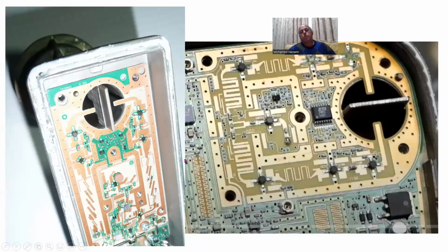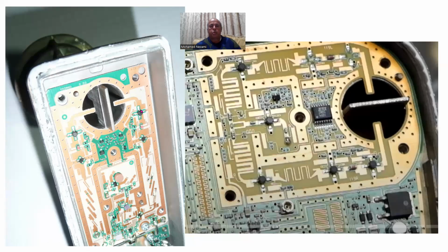Okay, I know we mentioned this in the design of microstrip to waveguide transitions back then. This is an LNB example I just happened to pick up. And on these boards, basically, you've got a circular waveguide and a septum in here, and you can see the steps, here they are. You can see this thing is sticking in, and what sticks out in here is a piece of metal that will act as a short once we have a cap that covers this.